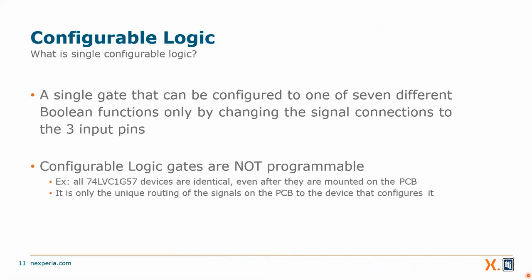Another function that is similar to this is the configurable logic device. A configurable logic device is sort of like a regular logic gate, but I can define its function depending on the way that I wire the part up. Now, a key thing, configurable logic is not programmable. I don't need a special programmer or any type of function for it. All of the devices are exactly the same.